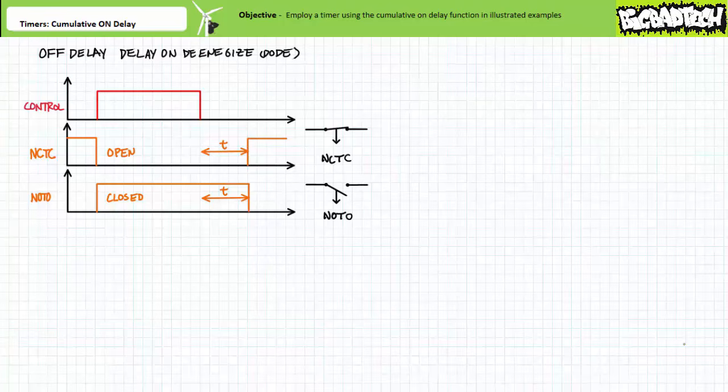Note the different terminology and schematic symbols employed by the off-delay in comparison to that of the on-delay. They're opposite, as one would expect. An off-delay could be used to keep one motor running for a measurable period after you turn another one off. Note for this general purpose orientation, I've purposely simplified the timing diagram of an off-delay timer.